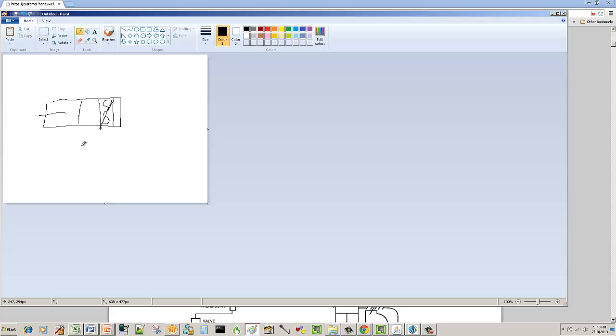Now here's the thing. Typically, for cooling, the method we use is to introduce between 55 and 65 degree air, and you rely on air changes. The air changes are going to change that temperature because your heat's going to float to the top, your cold air is going to settle on the bottom, and you're going to change the volume of air. Maybe you're looking at 6 to 8 air changes. Maybe you're in a hospital, you're looking at 20. But you're changing the volume of that air. That keeps particulates and pathogens out of the air, but it also helps cool a space down.